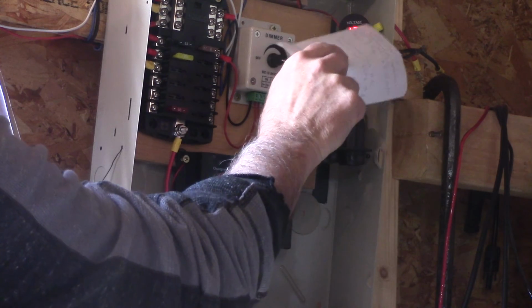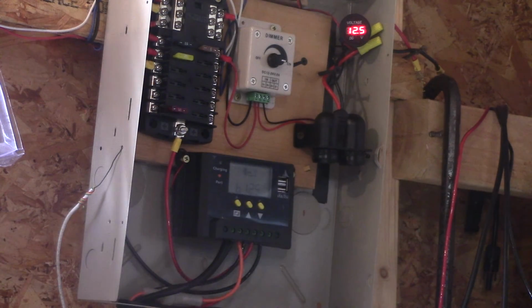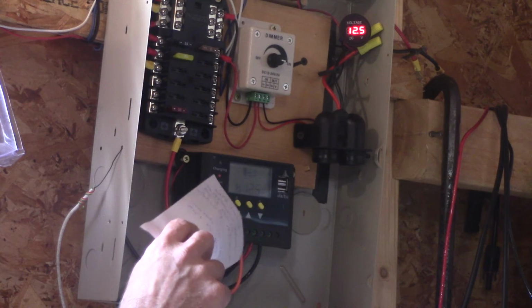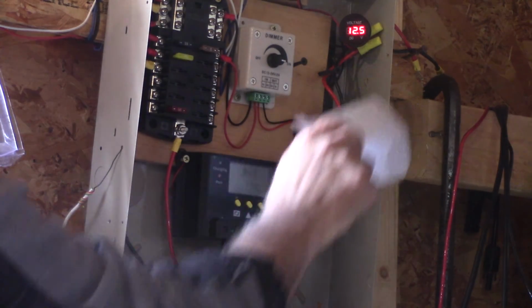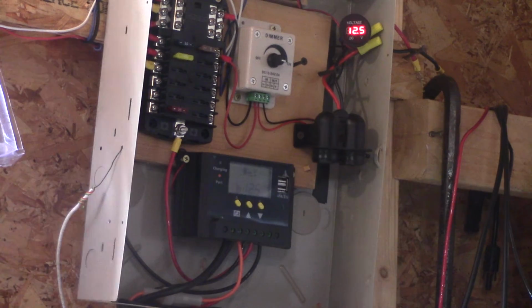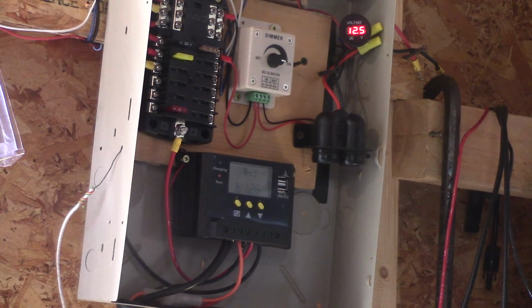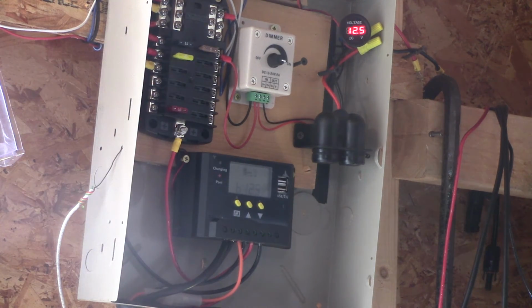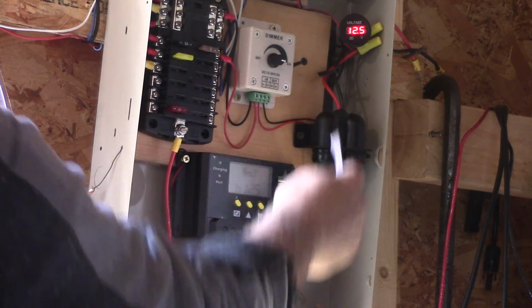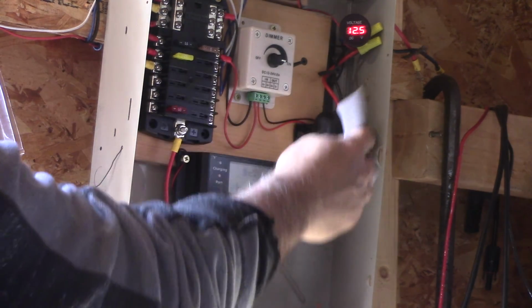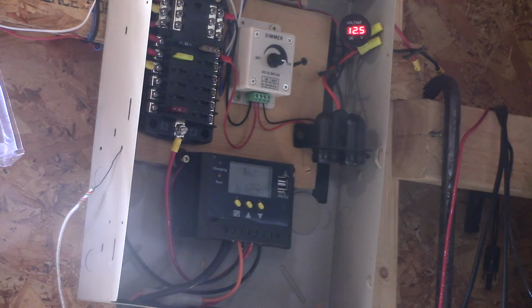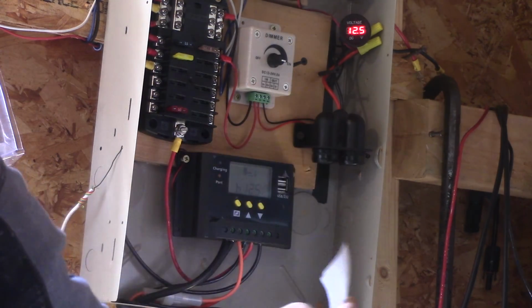Also, I just wanted to share, run an extra voltmeter. Anytime you're running charge controllers, things fail, things can get out of calibration. You want to make sure that your voltages are matching because you don't want to damage your batteries and draw them down. And that's why we want to know watts. We want to know the maximum drawdown potential of our circuit in watts so that we know how long we can run our lights and, say, our Gable fan like I do with this little circuit we're running here today. This thing out in the field I run can be charging 4 different computers, cell phones, or I can be charging a ham radio station, several of them, or I can be doing other things.